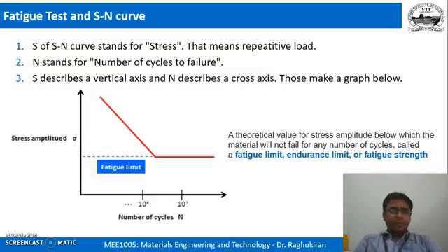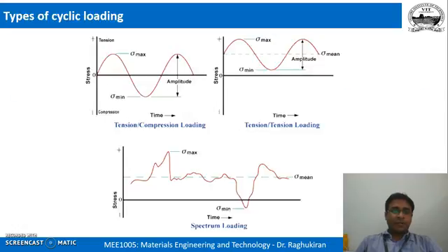Similarly, even for the fatigue test, okay, fatigue strength, what we do is we conduct a test. In fact, it is a collection of tests, by taking a number of samples and varying the stress amplitude. In the previous case, you have seen the kind of stress cycle, right? We have something called amplitude here. What is this stress amplitude? Or here it is maximum stress. The quantum of stress is this much, and what kind of stress? It is tension compression. It is tension.